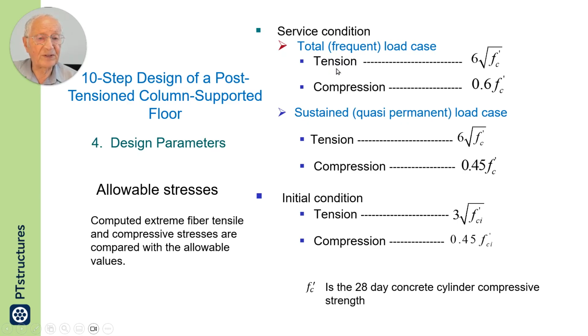For frequent or sustained load, total load combinations, sustained load combinations are a little bit different. The difference between the total and sustained is that total is the load given in the code for which the slab has to be designed.